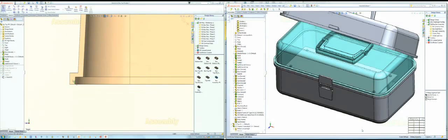On that sketch, I created a sketch that went from this point to this point to this point back to the bottom. And I made the sketch without creating references, which you can do in your tools, or if you create references, just blow them away and just hard dimension this and sweep the cut. And once I do that, I can go out and take the lip and groove feature and just delete it. So I've used the lip and groove feature to actually create the geometry I needed. Now I just copied over it and then blew away the original. Okay.